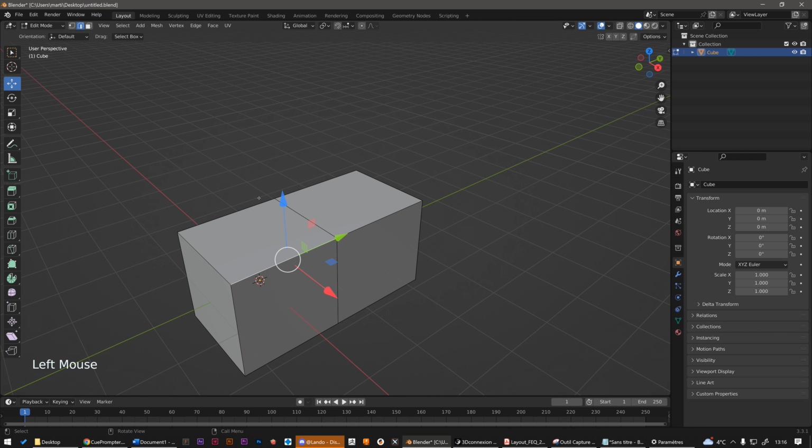On the other hand, if I create a new edge from this vertex, with the knife tool for example, whose shortcut is the K key, if I add an edge here, the vertex now belongs to 4 edges, and therefore if I select this edge's loop with the Alt key, the loop is now extended through the vertex. I hope all that makes sense.